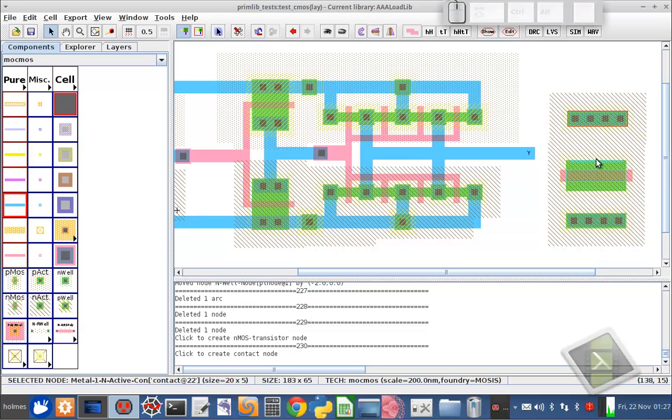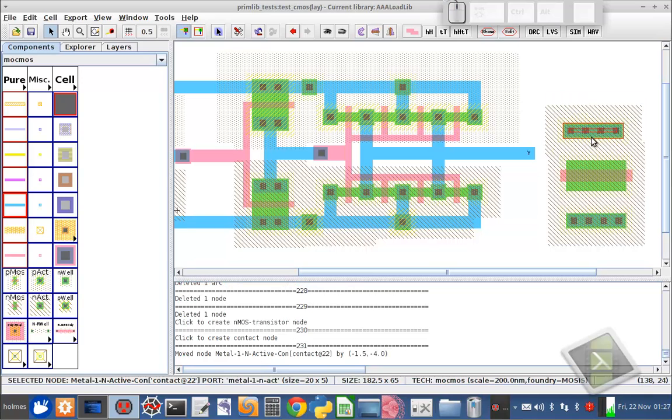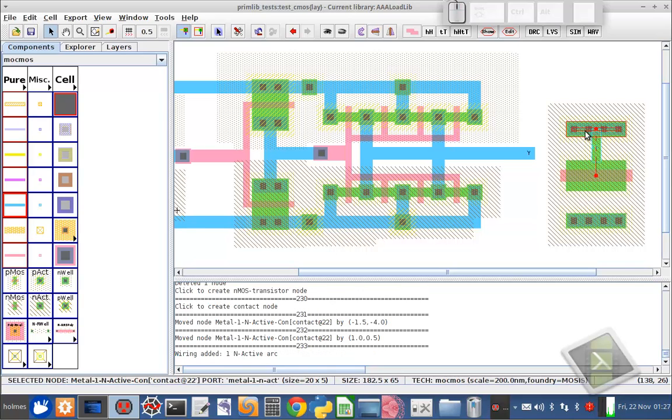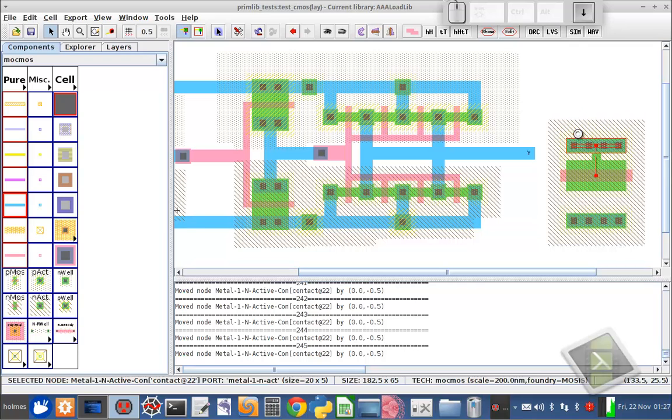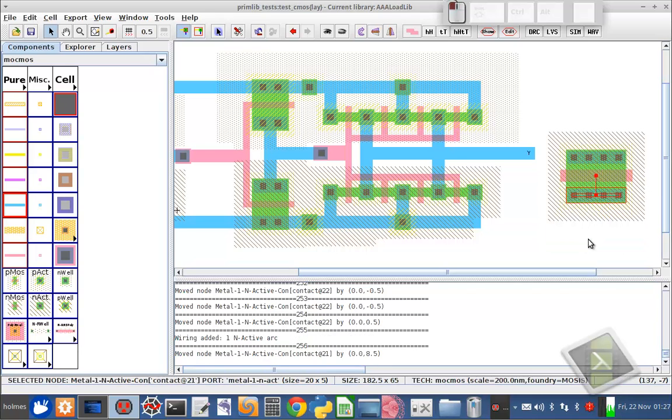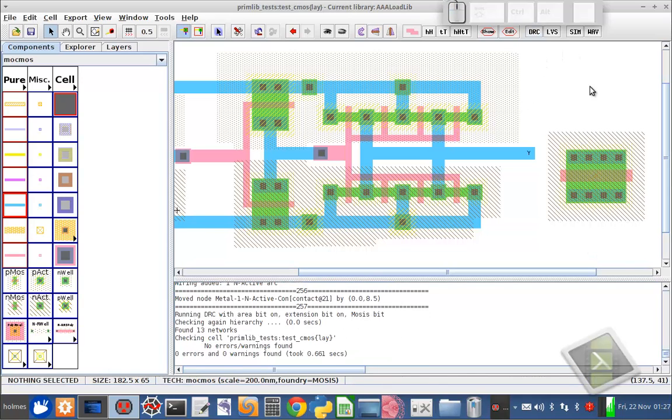If I look at the connection here, I select it. The pin is highlighted here, so I'm using the right mouse button to select that connection. Left mouse button, then finish with right. Those two are connected. Now that arc in the middle looks very narrow, but if I reduce the length to 0, it will satisfy the rules. And likewise, if I connect here to here, I can walk it in, and I've got an N transistor. So there's the simplest construction of a transistor.